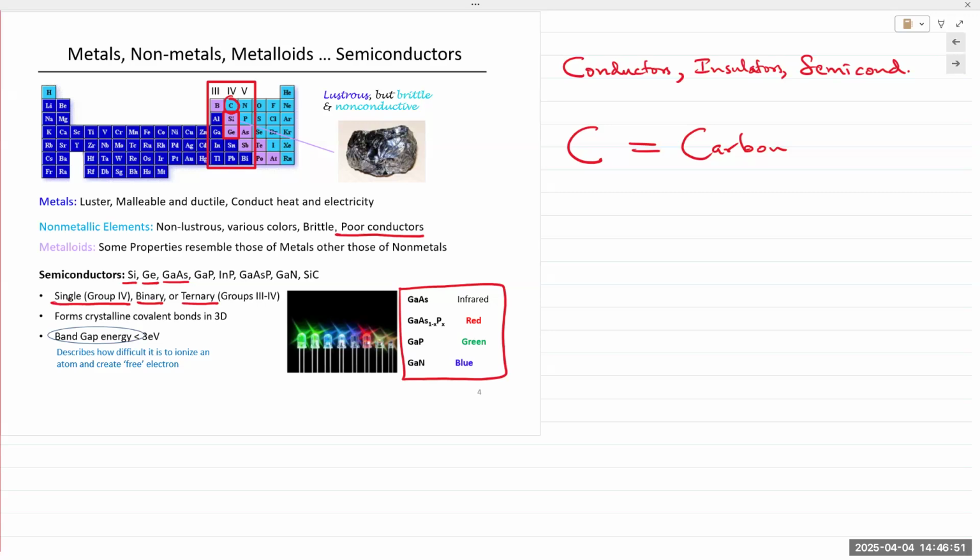Now the bottom is EV, valence energy, meaning the electrons have enough energy to stay in the valence band. But if they acquire enough energy, they can jump to the conduction band and they are now free to conduct. It's not a physical jump, they're just acquiring sufficient energy. This is what happens when photons are incident on that semiconductor diode. The photons are imparting energy to those electrons. The electrons acquire that energy and they are now free to conduct. But this is a material property.